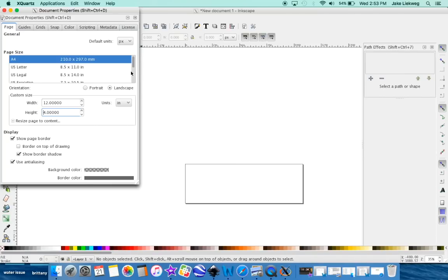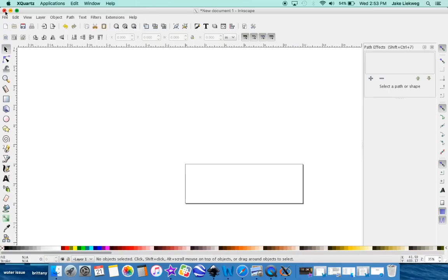So now that I've done that, you can exit out, but before I do that, I'm going to change my default units to inches, which right here, that's what that changes. If you watch, I'll change it back, or there's millimeters, and change it back to inches. Once you do that, you don't have to hit enter. All you do is come back up, exit out, and it keeps it that way.